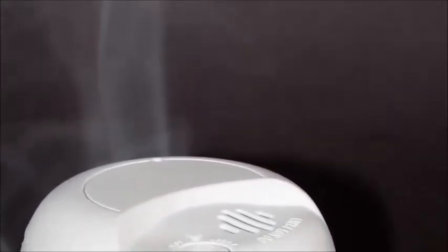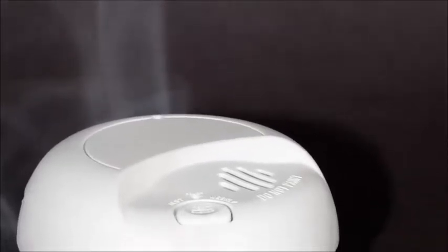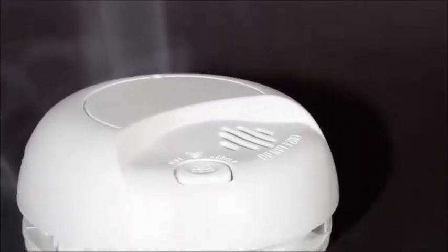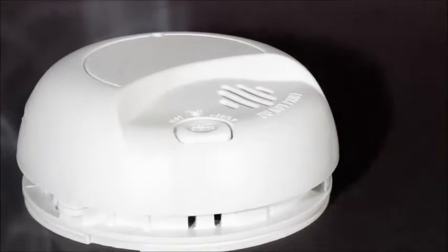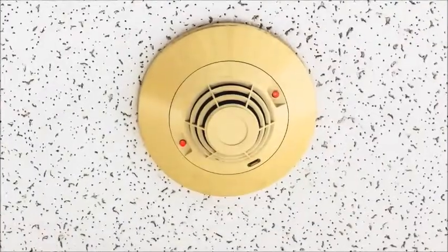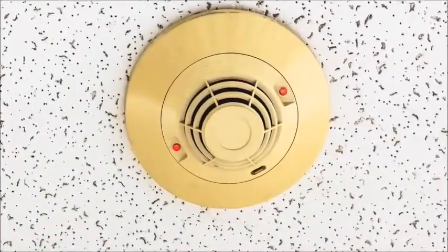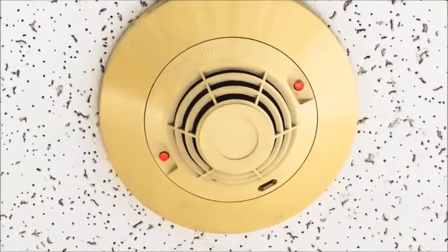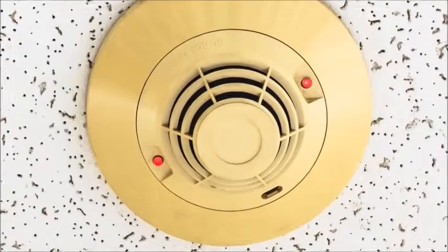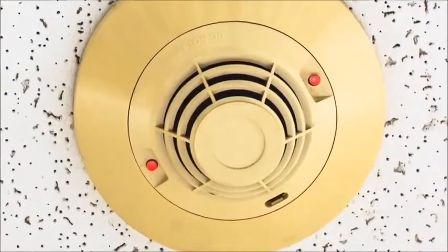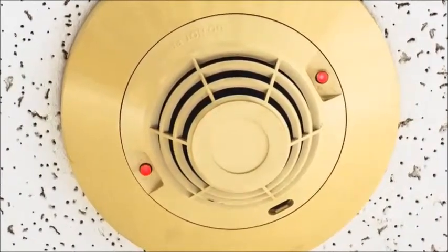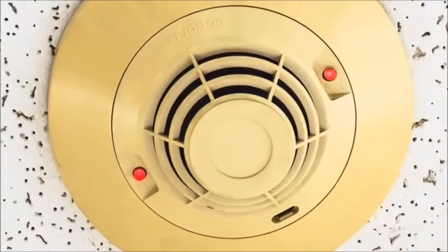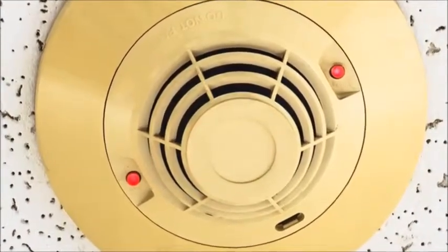Should the system detect any type of negative environment, such as small amounts of smoke, small changes in temperature, or flickering light, as from a flame, it can notify the appropriate personnel in many different ways. Multiple levels of warning can trigger different responses depending on the stage of the fire, from simply notifying personnel of a pending problem to communicating with a fire alarm control panel to adjust air conditioning or release different types of fire-suppressing agents, or all of the above.